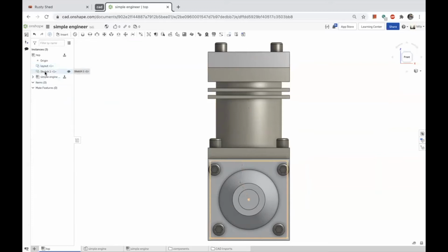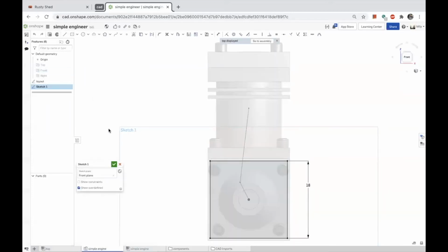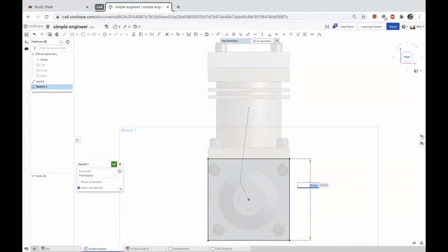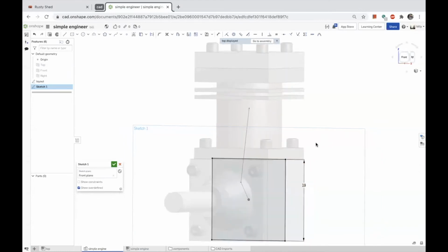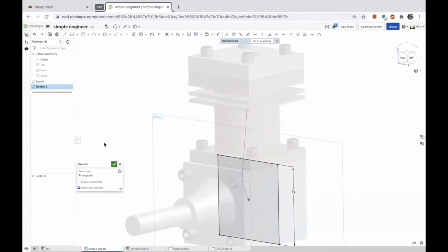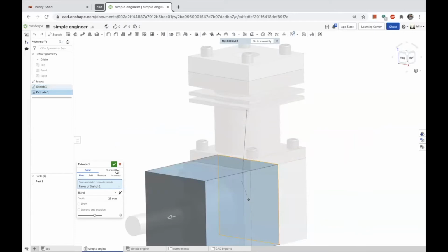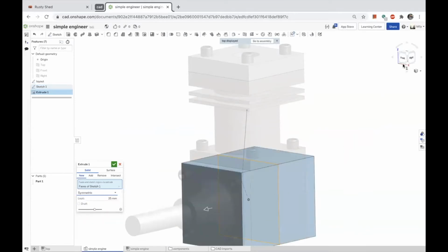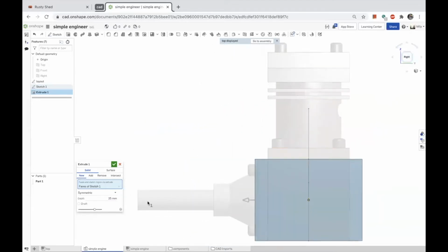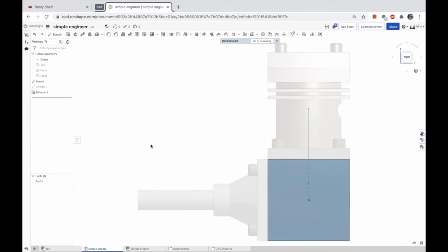All right, I want to go and edit what I'm working on. Fixed. Change this to 19. Yahoo. Okay, with that, I'm going to extrude it, and I'm going to go symmetrical. And by how much? You can actually move it, and that's about that much. So 19. Okay, new.